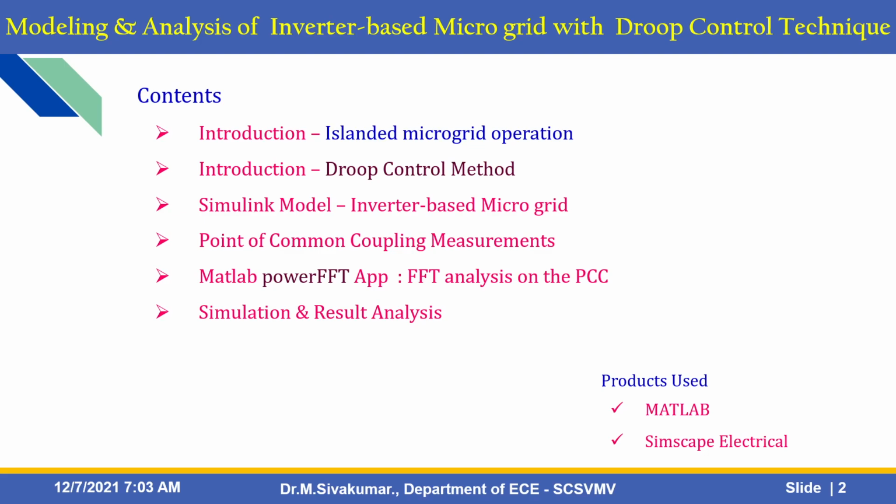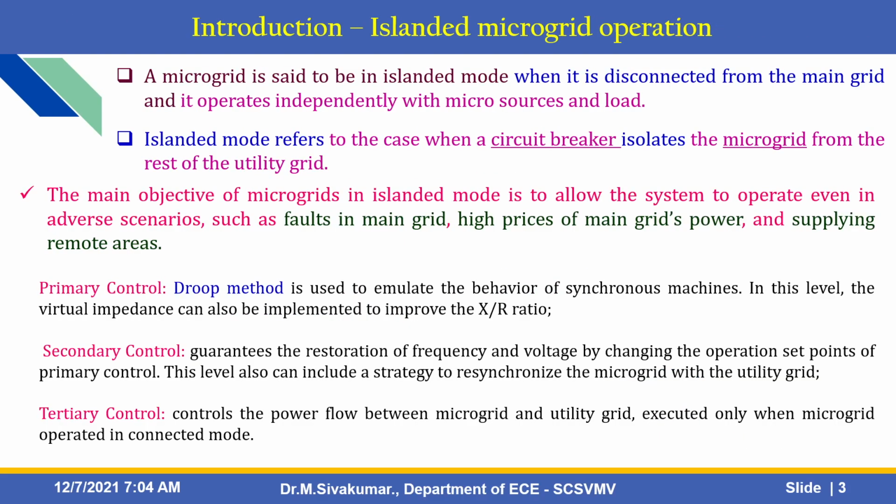What are the products you need to design this inverter-based microgrid with the droop control technique? That is Matlab and the Simscape Electrical toolbox. Here is a small introduction about islanded microgrid operation. First, you will see what a microgrid is.